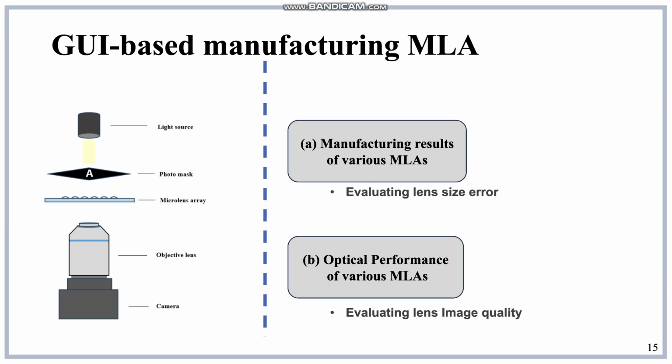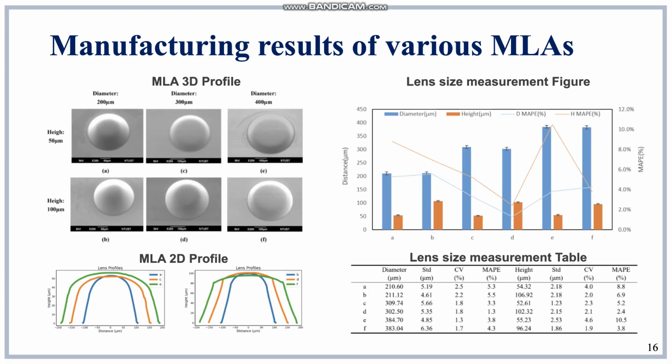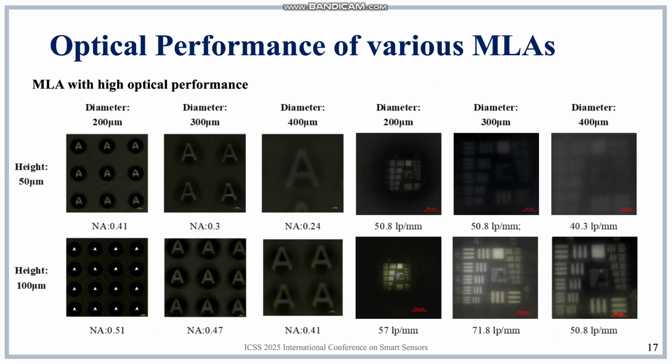Here we show the manufacturing result and optical performance of various MLAs. The system achieved high precision with dimensional errors mostly under 10%, demonstrating suitability for high-resolution optical systems. Optical testing using the USAF resolution chart confirmed high imaging quality.